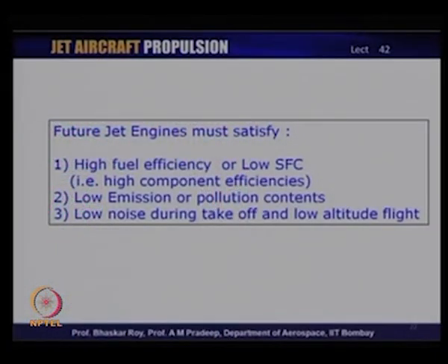In future, for the aircraft to be successfully flown, we need to have three very important points in our mind. One, it must have very high fuel efficiency or low specific fuel consumption, which means that every component of the engine, that is the intake, compressor, combustion chamber, turbine and nozzle, all of them have very high efficiency of operation. That is absolutely necessary to have high fuel efficiency during all kinds of operation, not only during design point, but also during various off design critical operating conditions.